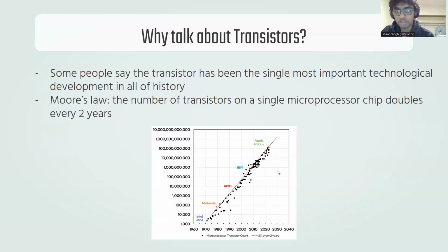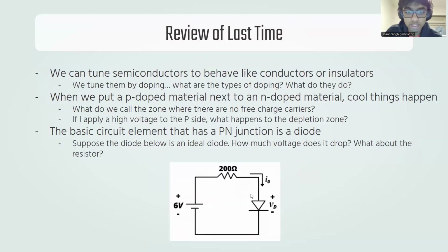So now we have our preliminaries on PN junctions established. Yeah, Atarf. Why would you even need the diode in the last circuit? You wouldn't, right? But say maybe the 200 ohm resistor is something that gets damaged if it has current flowing in the wrong direction. And say I'm dumb and I attach that battery in the wrong direction. Well, then I would accidentally be killing my resistor. I'd be breaking it. And this diode would make sure I don't do that.